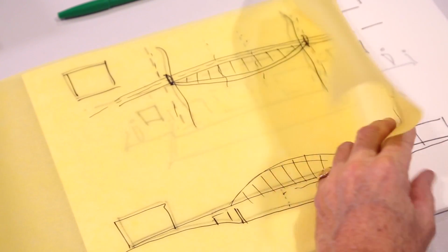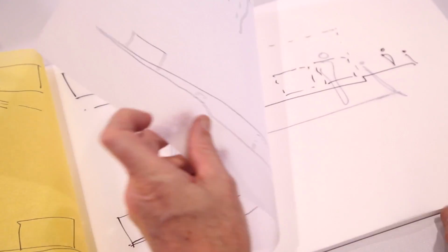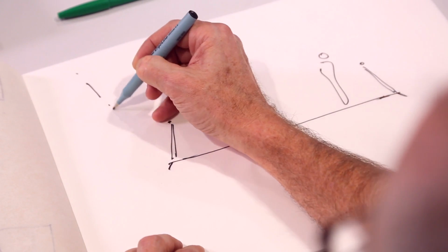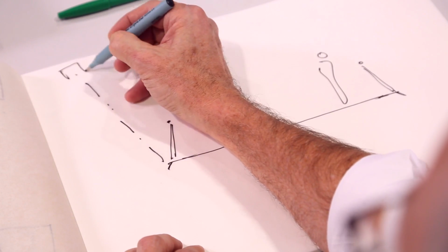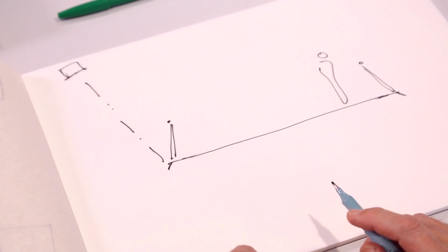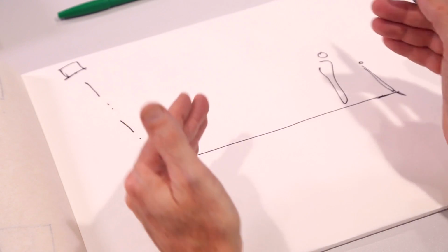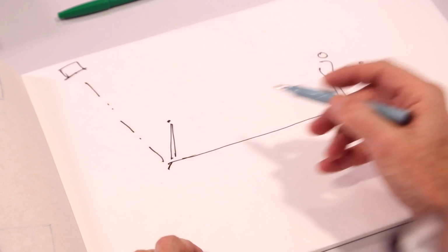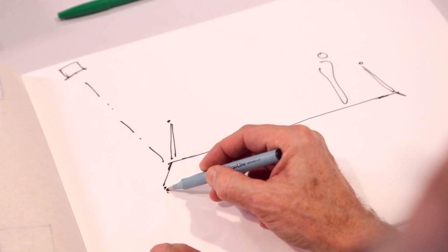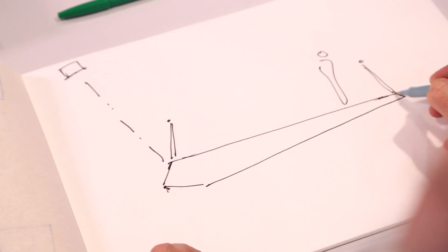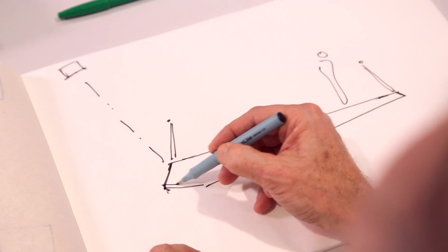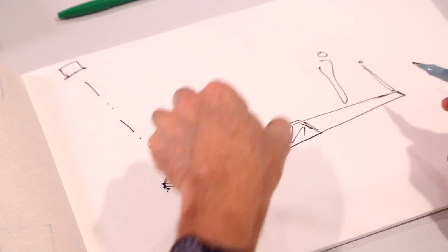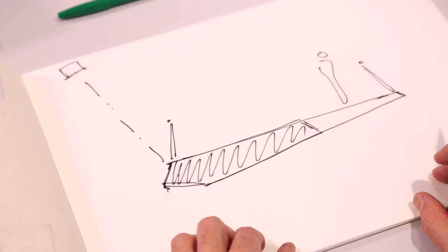What that does, of course, is that immediately when we come to our cross-section, we now have supports along one side. So our hangers coming from the arch, which is up here somewhere, are on one side of the bridge. That means that this thing has to have some torsional stiffness. You've got to restrain it from twisting at the ends, and you need to give it some sort of a box structure. So maybe it's a box girder here, maybe it's a steel box girder. So that's all a hollow box, and we've got some lightweight cantilevers on the outside.